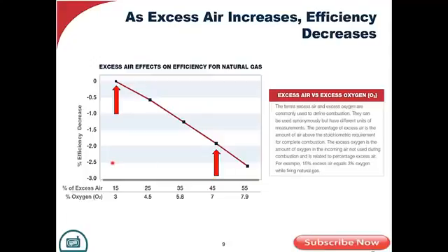So what we're saying here, when we talk about combustion, we're not talking about 100% combustion or 95% combustion efficiency. If you can hold 3% O2 most of the time when you're firing and handling load, we call this very effective combustion, good combustion.